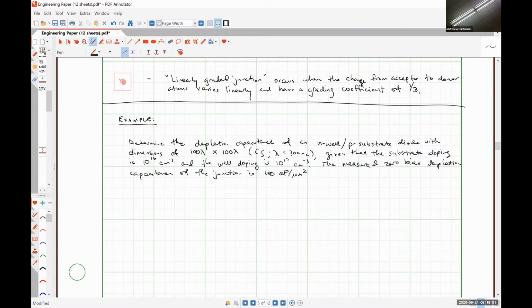And that's one thing that's actually kind of interesting about the numbers we're going to wind up using here. Whenever we talk about these capacitances, we really mean the capacitance per square. But it's not the same as per square that we saw with resistances, because we know that the area of the plates vastly influences the capacitance values.